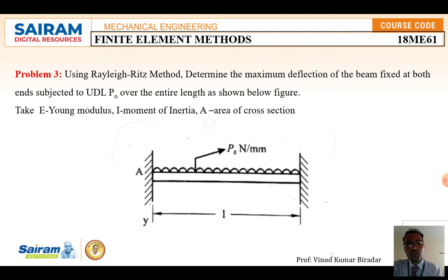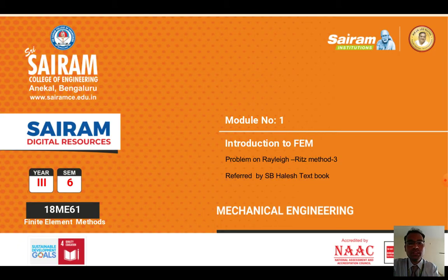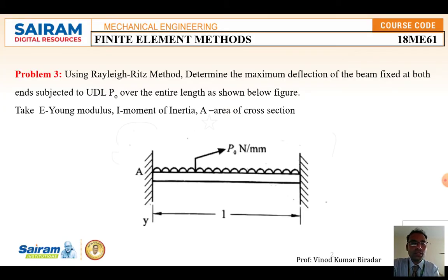After looking at the question, you have to analyze and remember the formula. You have to observe the diagram, whether it is a simply supported beam subjected to a UDL, uniformly varying load or point load, or a cantilever beam. Based on the given diagram and requirement, you have to note down the formulas for strain energy and work potential, and substitute them in the potential energy function equation.